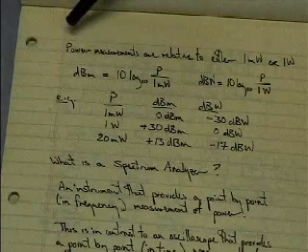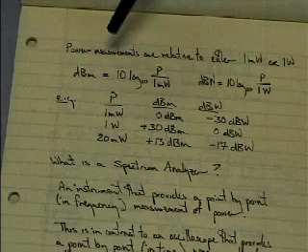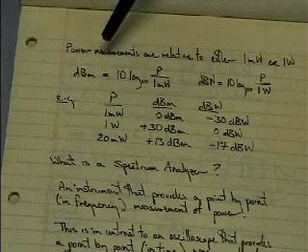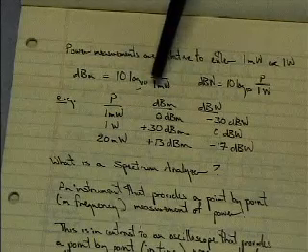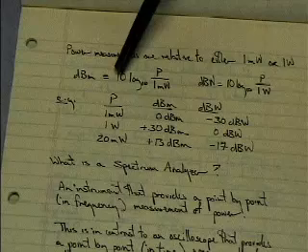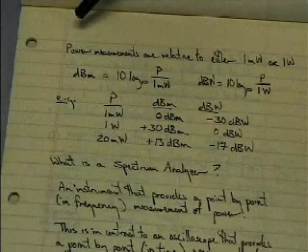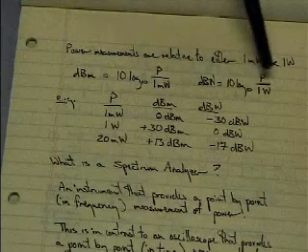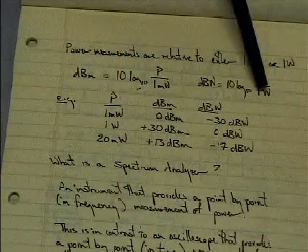If we're looking at a ratio relative to 1 milliwatt, which might be for very low power systems, we take our power, divide it by 1 milliwatt, take log base 10 of that ratio and multiply by 10. If we have a higher power system, for example a satellite that might be hundreds of watts, we'll take the ratio of whatever that power is relative to 1 watt.